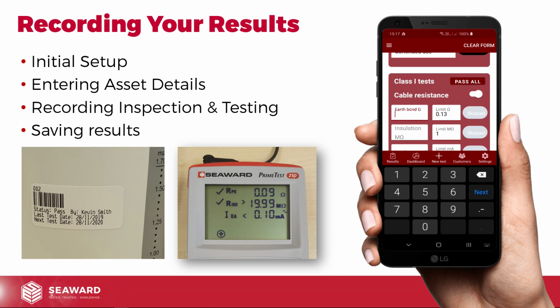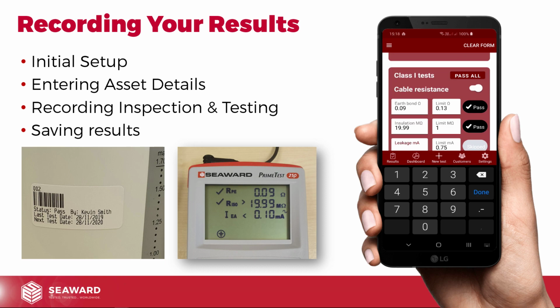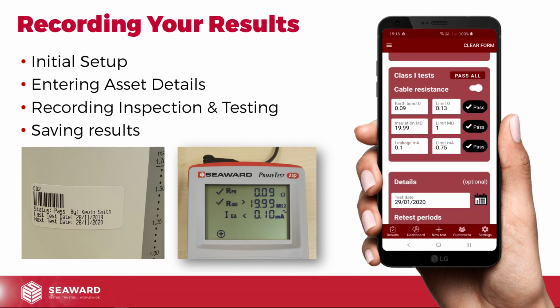The earth bond in this case is 0.09. Next. The insulation 19.99. Next. And the leakage 0.1. Done. So we've put those details in. All of those details are in, and that's gone straight off the screen of the tester when we've done the test.